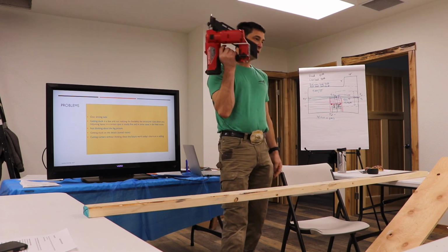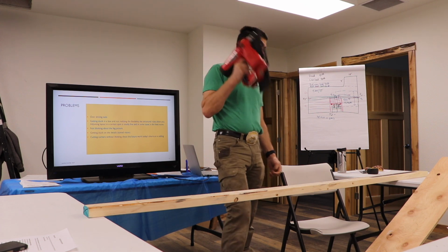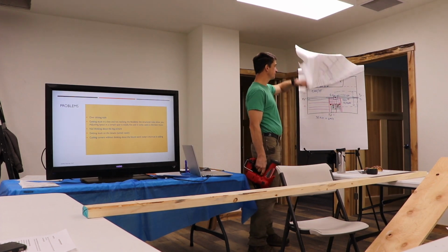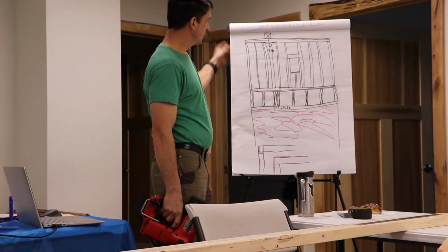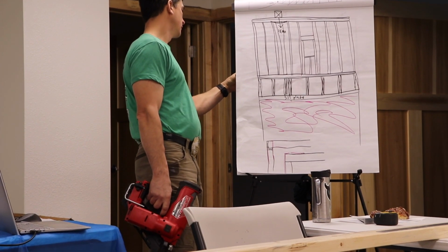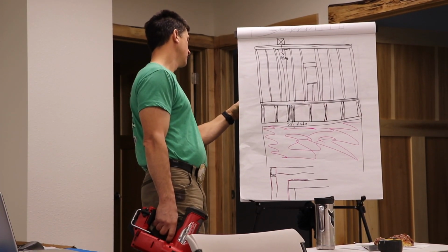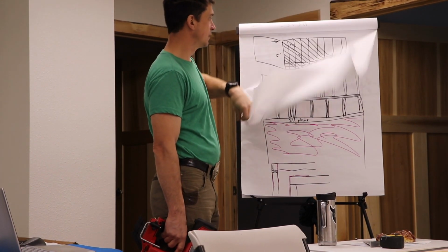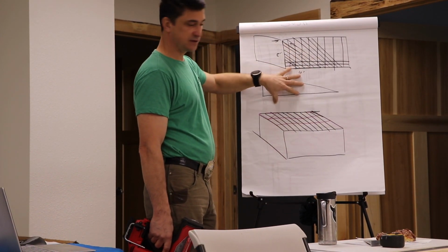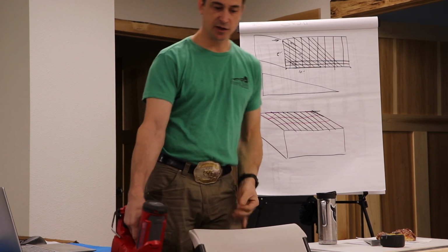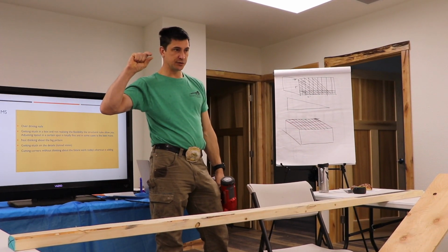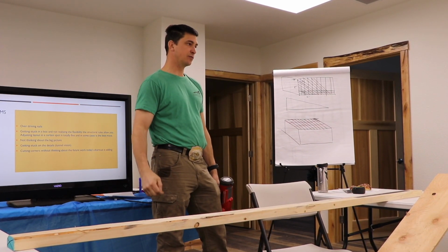But if you're overdriving, if you're driving halfway through the sheathing, all of a sudden we don't get the bracing that we need, because instead of this nail holding on a 1/2 inch of sheathing, it's holding on a 1/4 inch, and the nail heads can rip out of that really easy.